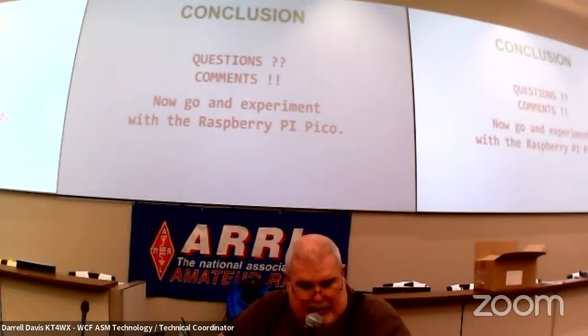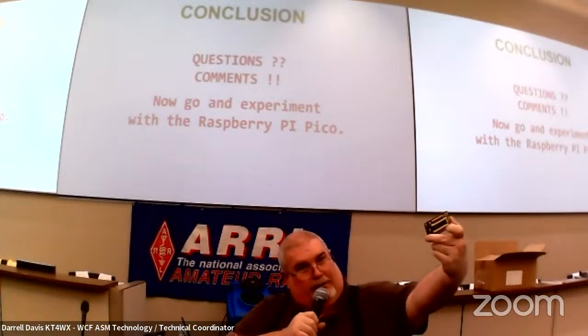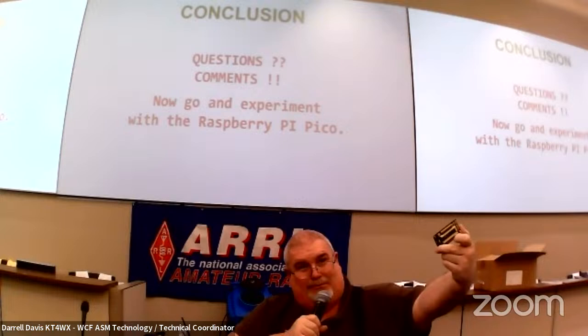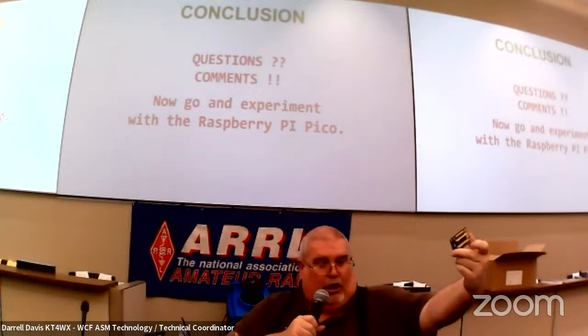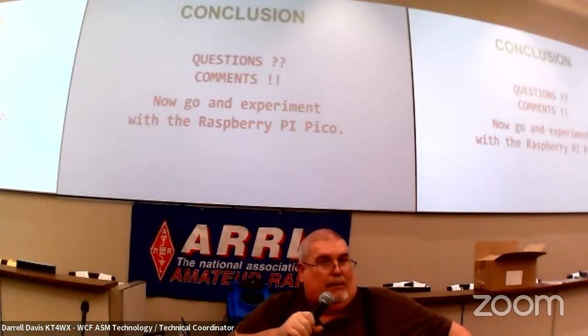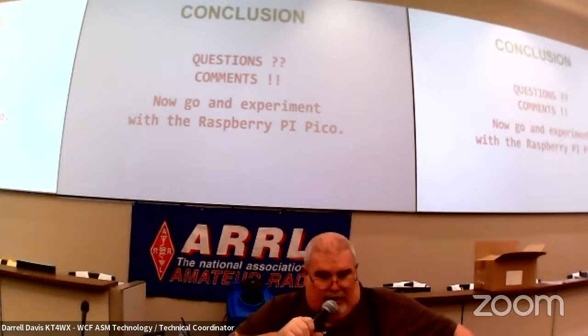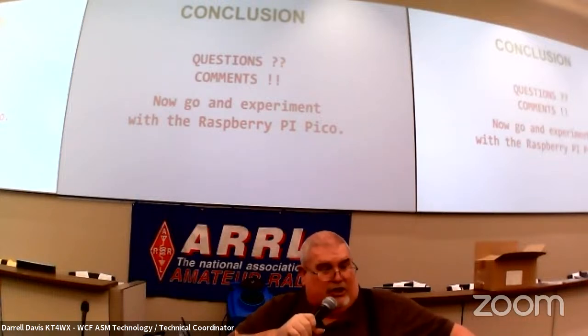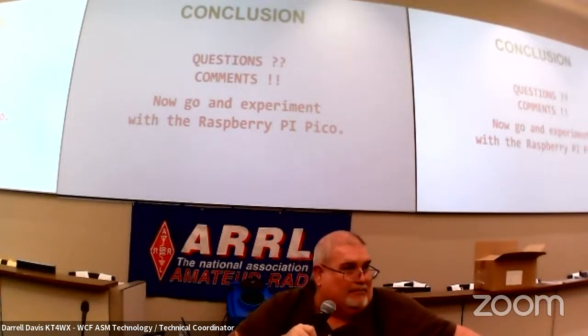Look at the header and look at the size of that voltage regulator. It probably doesn't draw more than 20, 30 milliamps, maybe 50 tops. I should have looked at the specs on that to see what the Pi Pico itself draws, but it'll be in the specification sheet. But the current draw is much lower. So if you need something for an embedded application that needs wireless connectivity, the reason they made the version without the wireless transceiver is that it draws less current.